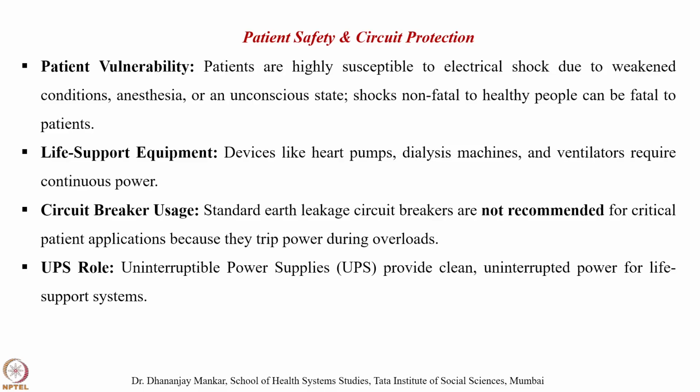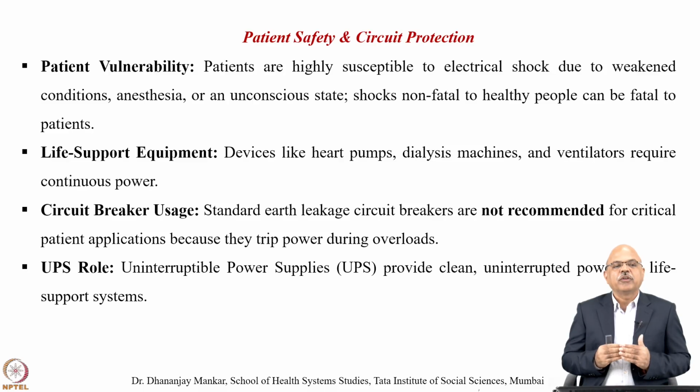With respect to patient safety and circuit protection, patients are vulnerable because they are highly susceptible to electrical shock due to weakened conditions, anesthesia or an unconscious state. Shocks that are non-fatal to healthy people can be fatal to patients. Life support equipment, devices like heart pumps, dialysis machines and ventilators, require continuous power. Circuit breaker usage: standard earth leakage circuit breakers are not recommended for critical patient applications because they trip power during overloads.